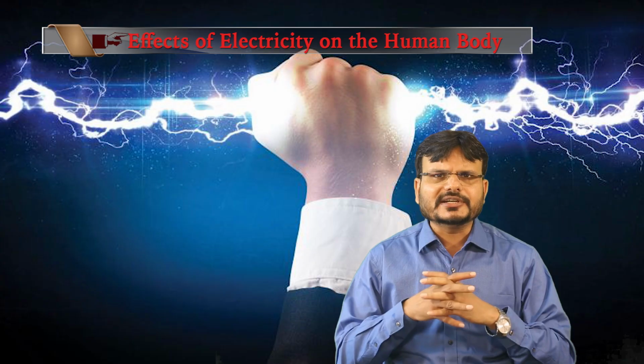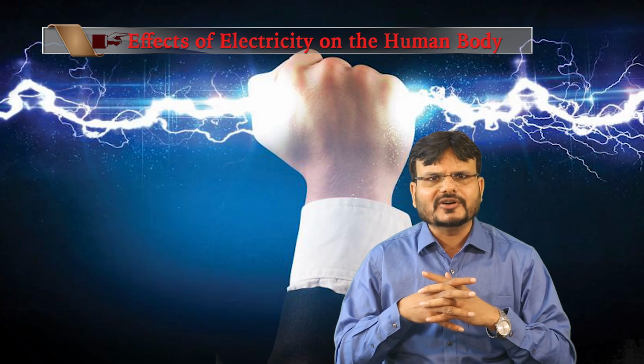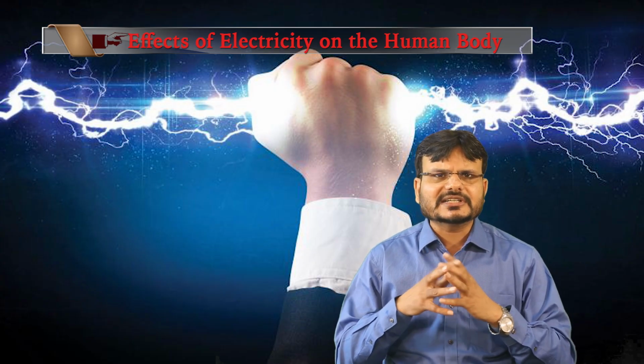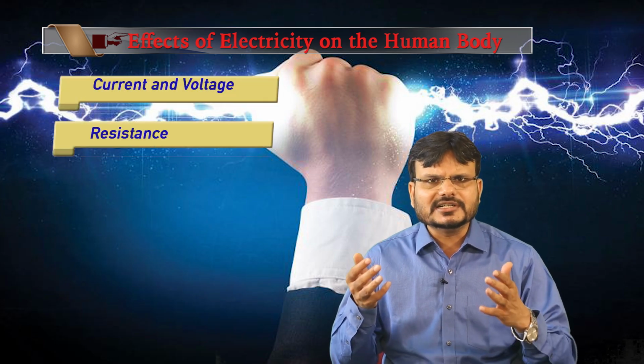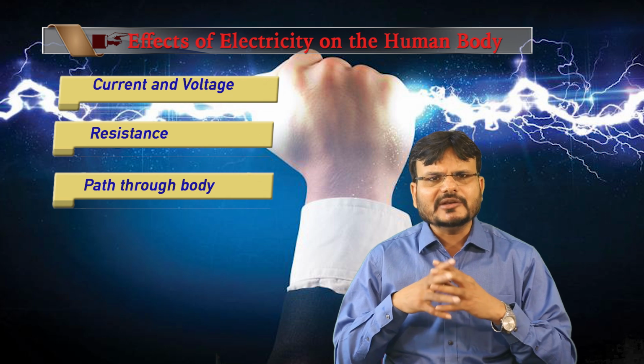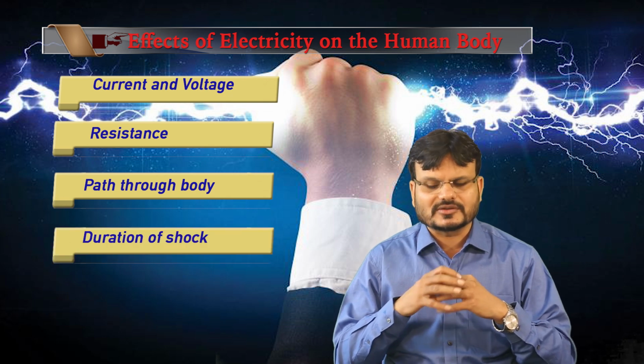The effect of electrical shock on the human body depends on several factors. The major factors are current and voltage, second is resistance, third is path through the body, and fourth one is duration of the shock. The muscular structure of the body is also a factor, in that people having less muscle and more fat typically show a similar effect at lesser current value.